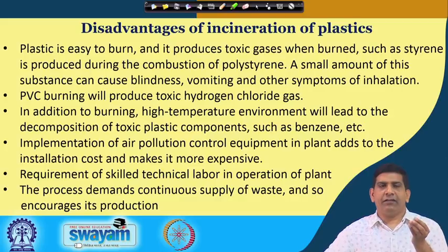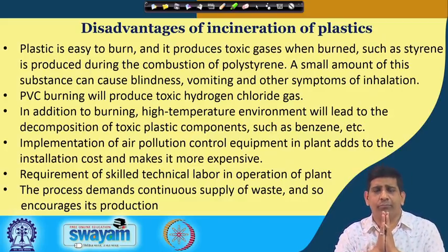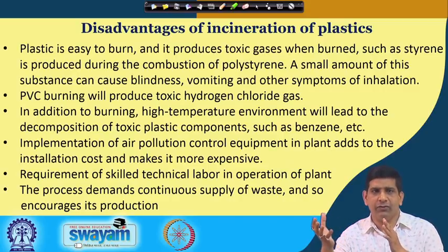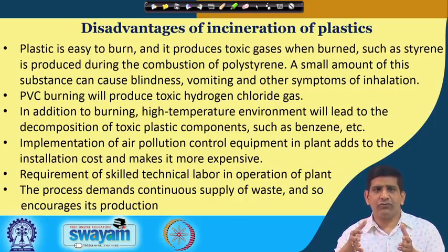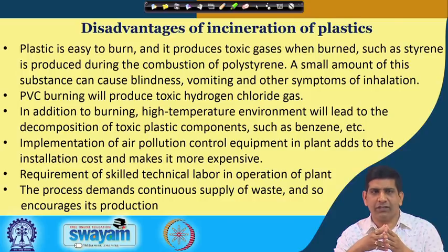So, essentially, that is the common criticism that we get for waste to energy plants: it is actually a negative to recycling, because most of the plastic we are talking about today, and also other components, if you look at paper and textile, have good calorific value. Plastic has pretty high calorific value. So, if I am setting up a waste to energy plant to deal with plastic waste along with my other municipal solid waste components, the recycling of plastic may get a negative kind of push.